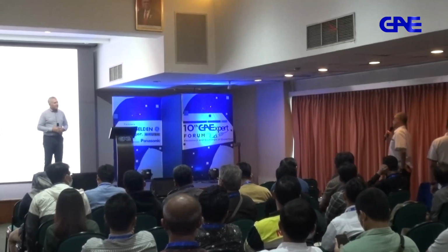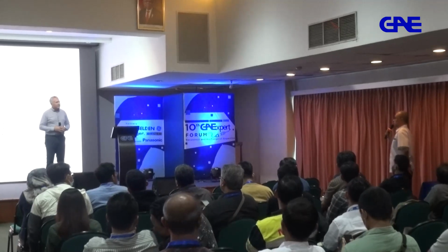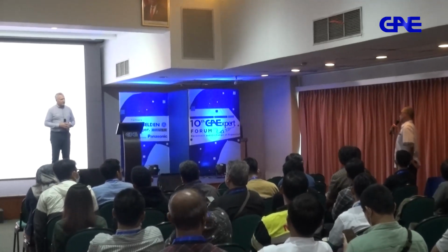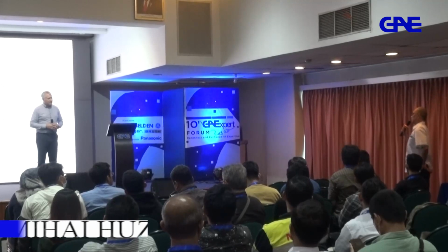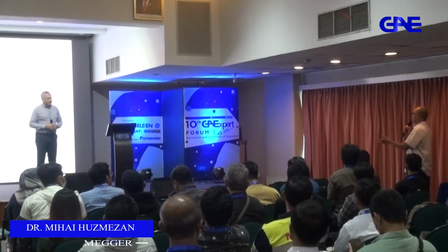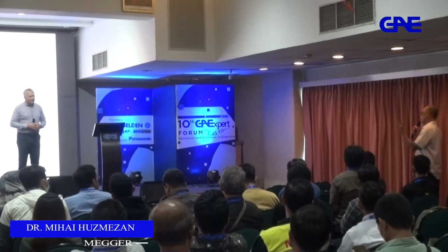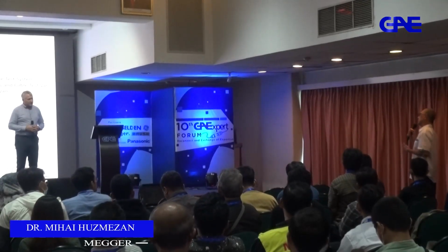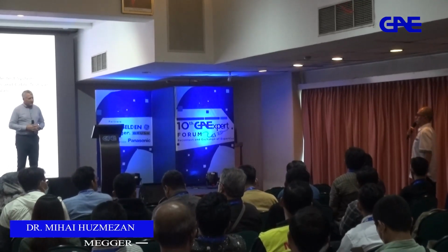My question is, when we test the switchgear using PD, and we get all the information after testing, the curve or picocoulomb or dB, whatever, the most important thing is we have to give a recommendation to our client.